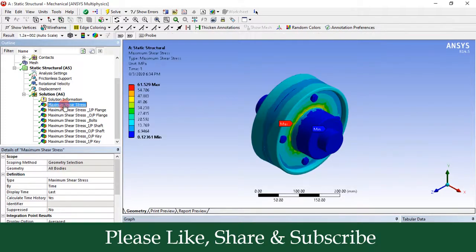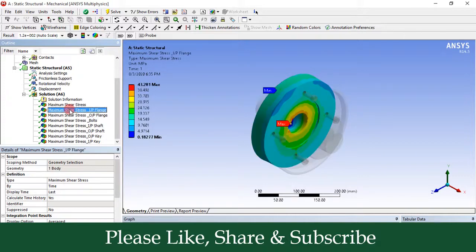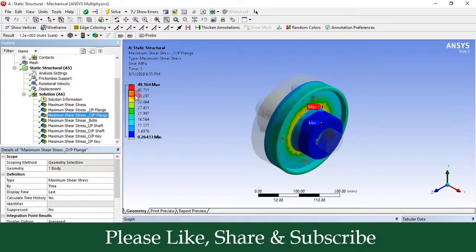So this is the result of overall coupling, that is maximum shear stress for coupling is 61.529 megapascal. Then this is the maximum shear stress for input flange, its value is 43.28. This is the maximum shear stress for output flange, its value is 49.164.